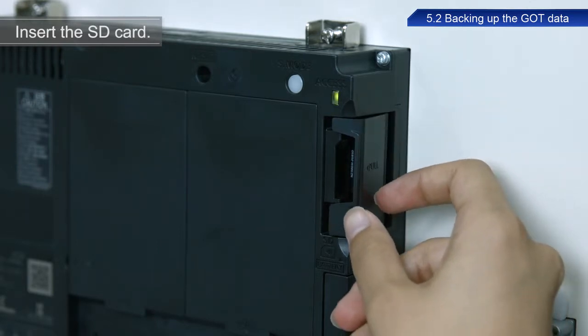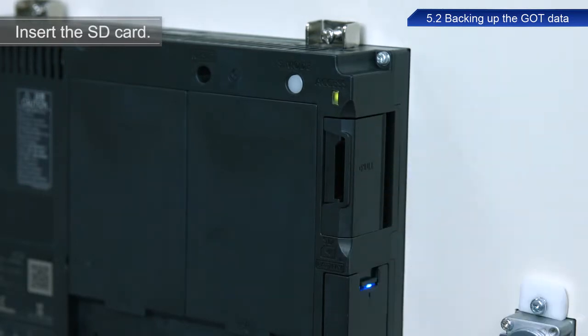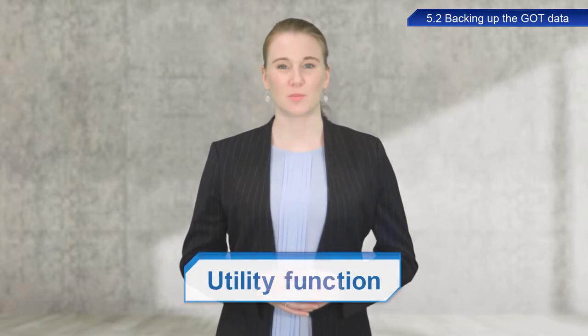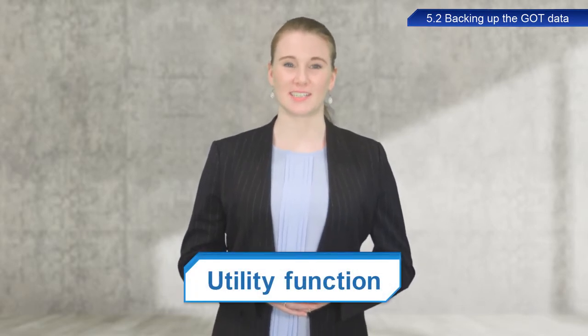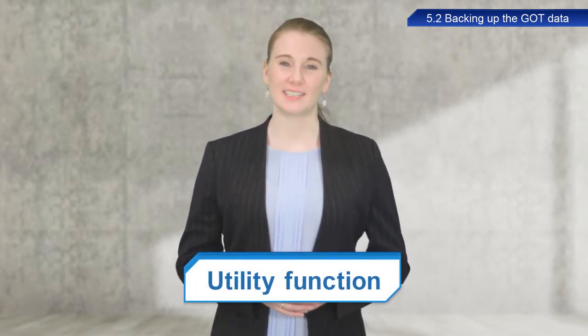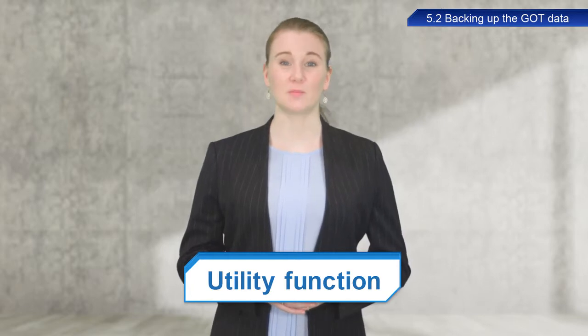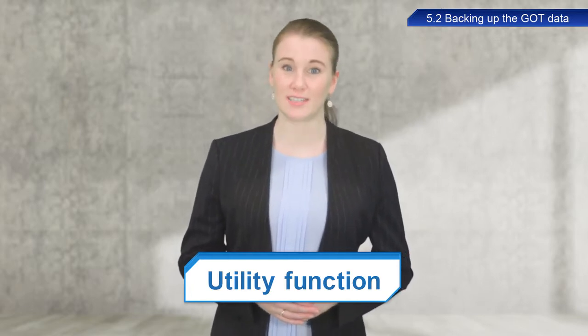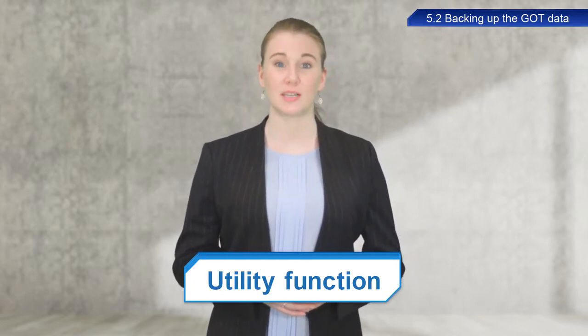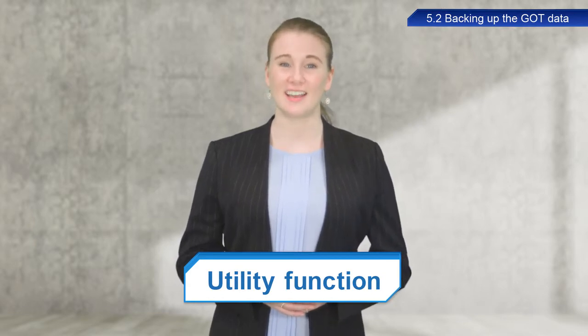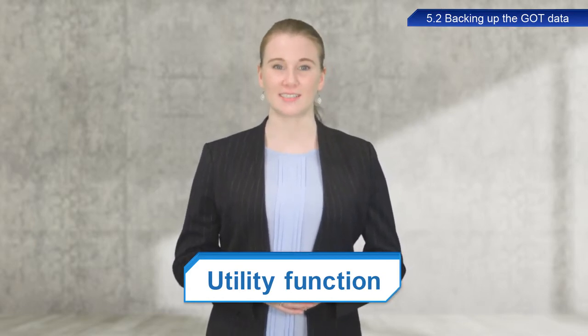Close the cover by pressing the cover until it clicks into place. The GOT can access the SD card once the cover is fully closed. Now let's back up the GOT data. Backups are performed using the utility function. Utilities are used to configure connections between GOTs and other devices, configure screen displays, manage data, and perform other functions.